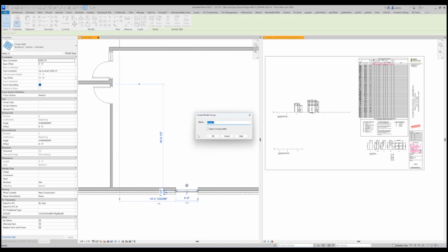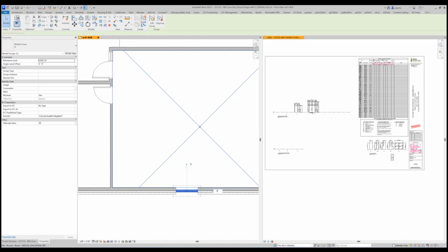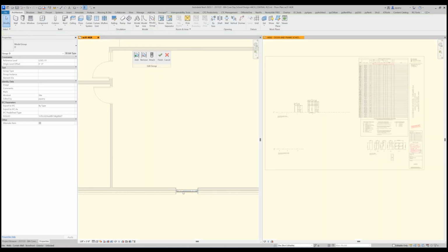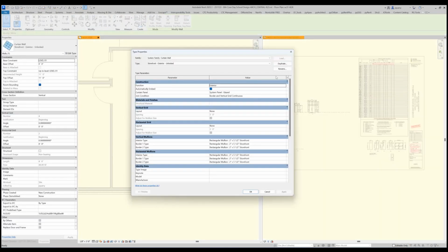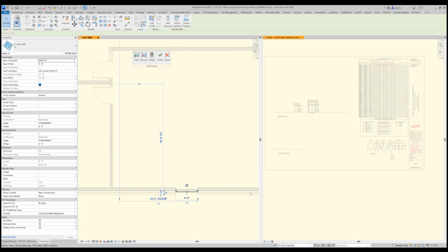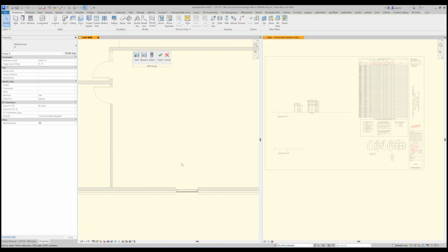Yeah, C's fine. Let's call it D. Yeah, so C or D, because the first four are obviously exterior, right? Yeah. So we'll call that D. So now you have a difference between door frame types or numbers, and window frame types or letters. So that's how you'll figure that out. So I'm going to duplicate this. Except we made our storefront window for the door an A. No, we made it number 3, or number 4. Sorry, that's right. All right.